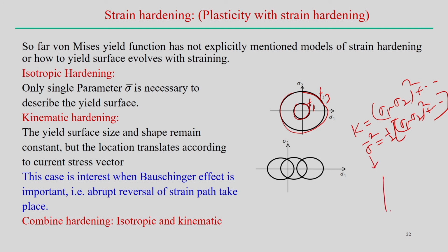This is the first yield point; the strain hardening effect means this is the yield point, which we can say is sigma 1. Now it can be sigma 2 after strain hardening, then sigma 3. So, it will follow this curve, and the analysis of following this curve will be in incremental mode. That way we will be able to evolve the yield surface and take care of the strain hardening effect.